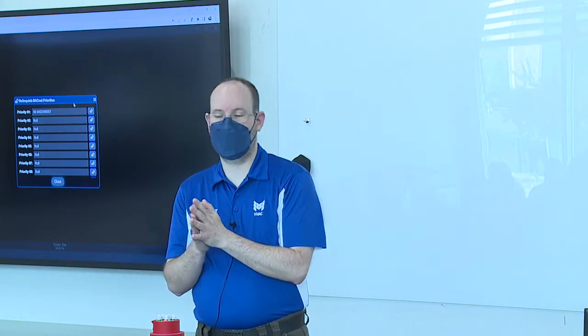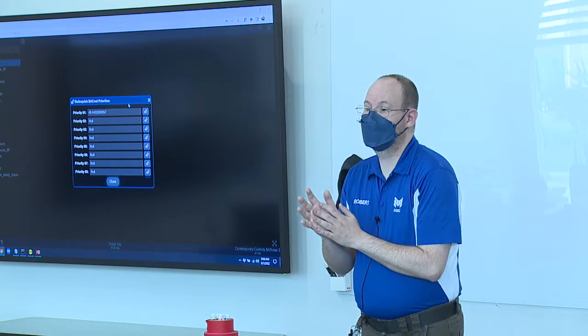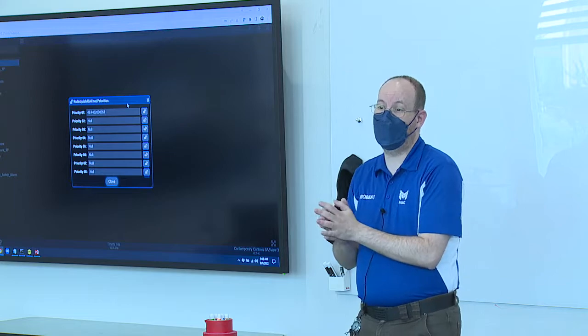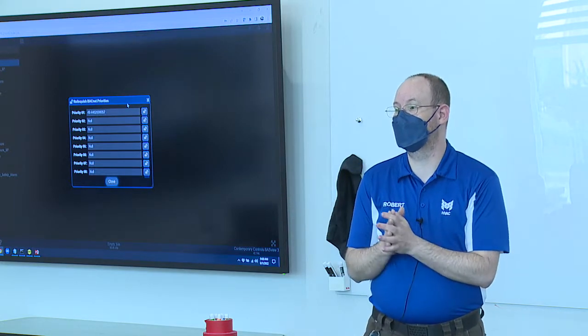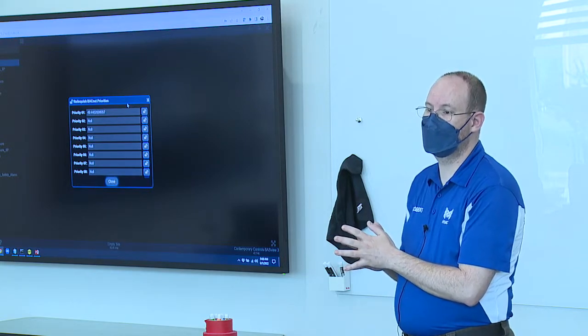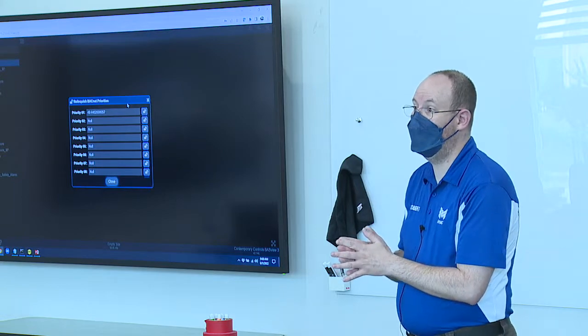So this is a read-only value? Not necessarily. Discharge air temperature should be a read-only value. I got around that by setting it at priority 1 so you couldn't overwrite it. I was wondering if that was the case, whether read-onlys were set at priority 1. No.